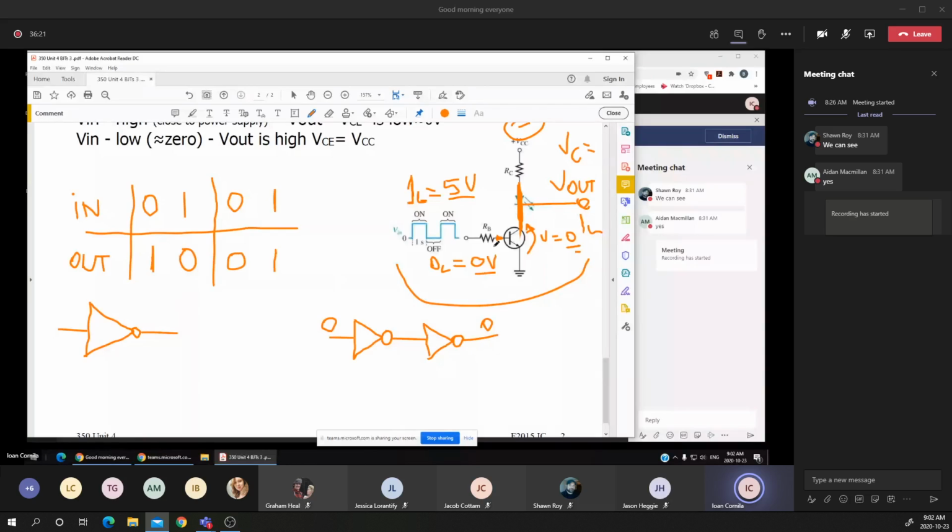In this way, by choosing two identical circuits, connecting the output of the first transistor to the base of the second transistor, I'm changing again the phase shift by 180 degrees, which means that the output of the two transistors connected in series will follow the input signal that is applied to it.